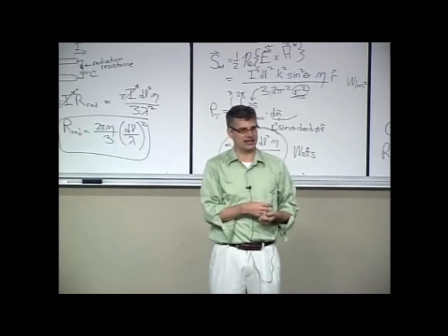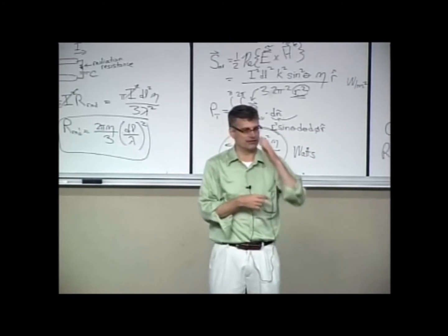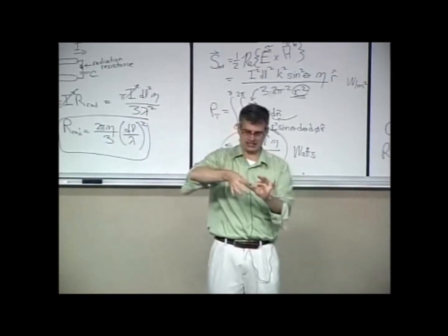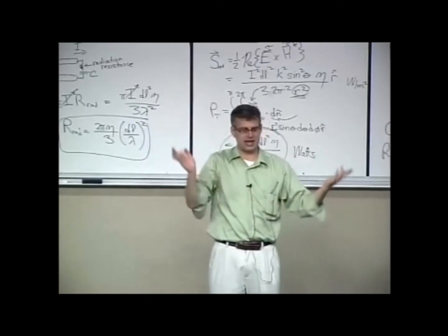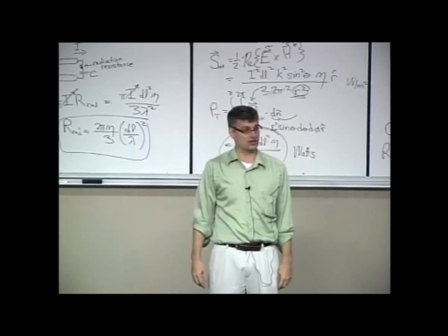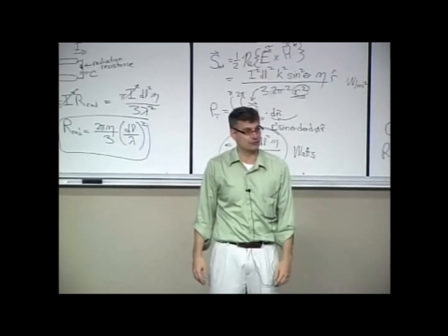So it doesn't matter that the wavelength of AM radio is tens of meters long. I just take a little wire, I whip it out there. Yeah, I'm losing 20, 30, 40 dB in inefficiencies, but the free space equation is so forgiving down at AM frequencies, it doesn't matter.